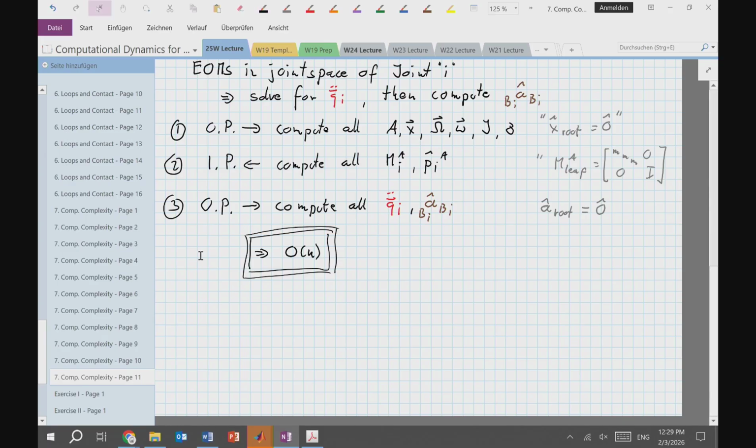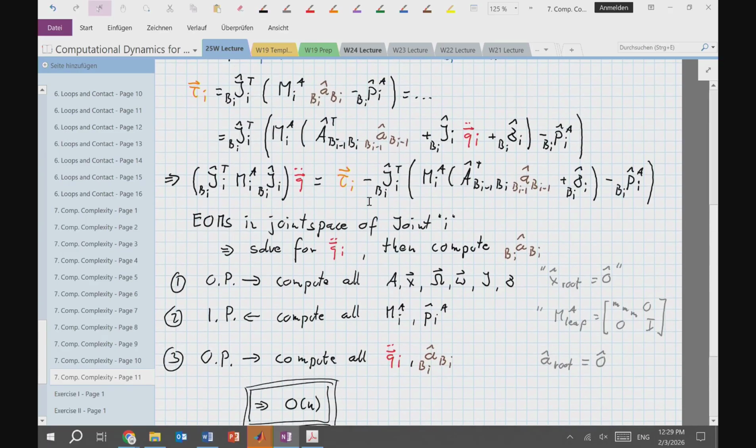And I think there's interesting information in there, right? If you ever have to tune a PD controller for this joint, there's often this question, what's the mass? If I have a PD controller, I want to set a certain frequency, but then your mass is somehow important. Well, there it is, right? That's your mass, and it's configuration dependent, which makes stuff a little bit more involved.